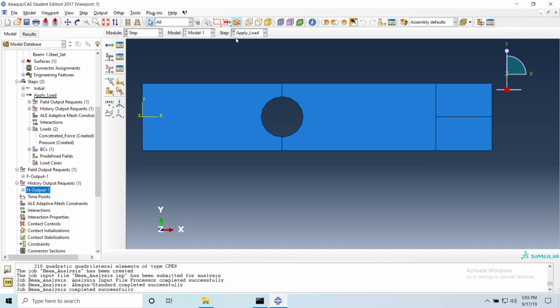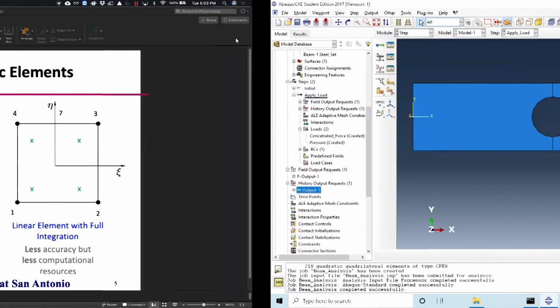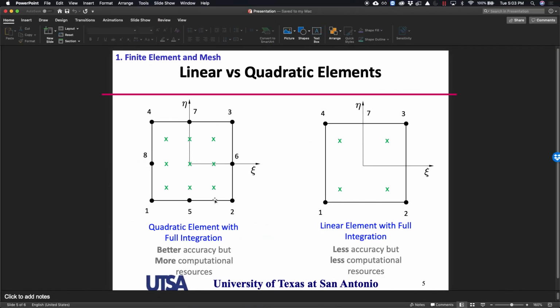And for example, if you request the stresses at an element, it's gonna give you the stress at the integration points 1, 2, 3, 4, 5, 6, 7, 8. So that's when this local numbering comes into place. Because if you have the stresses at node 1 of element 5000, it's gonna give you the displacements here. But it doesn't matter how deformed your element is, your S11 is gonna be the same for all the elements. It's gonna be x and in the x direction.